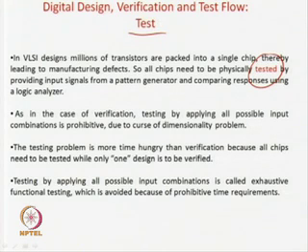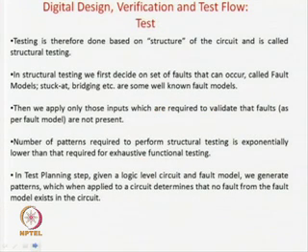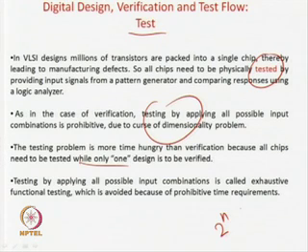So, again the curse of dimensionality problem is there. If you have n input pins, then you have to apply 2 to the power n test vectors, and you have to do this for all the chips. So, there is a big problem here. It is an even bigger problem than verification, because verification has to be done for only one design, and testing has to be done for all the chips manufactured. So, if there are n inputs in the circuit and you are trying all 2 to the power n vectors, that is called the functional testing of the circuit.